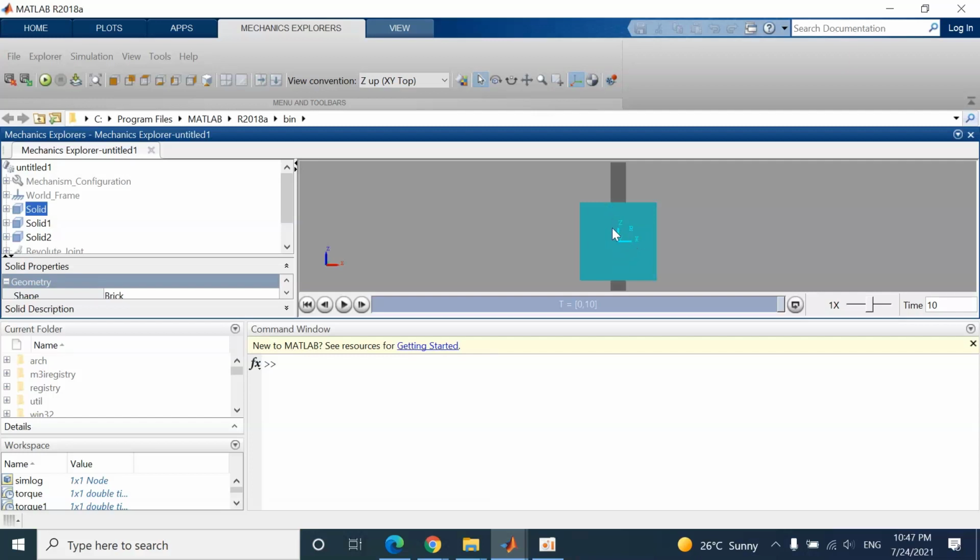As you can see, the z-axis is not in the right position, and it should be perpendicular to the page because we are using revolute joints, and we should change it. If you click on the toggle visibility of frames, you can see the component frames.